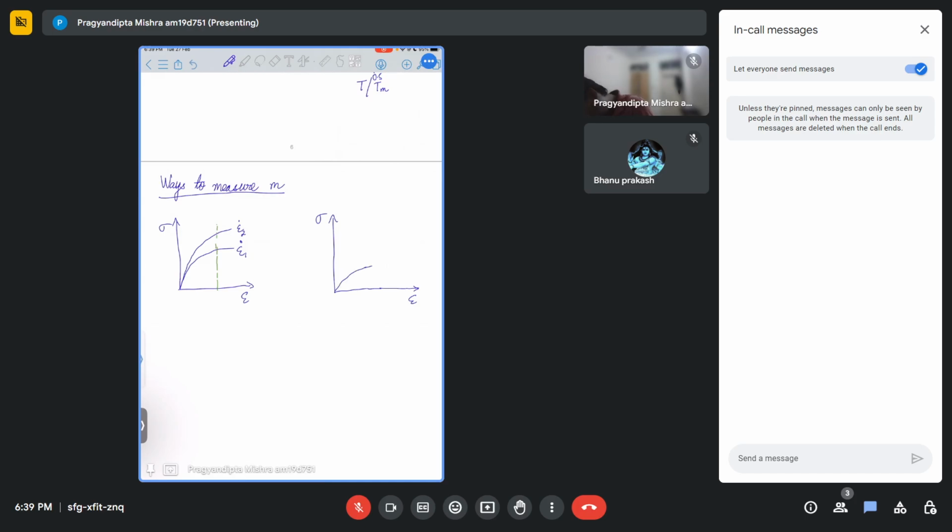Okay, and then change the strain rate. So there'll be a sudden change to a new value. Okay, so this is at epsilon 2 dot. This is at epsilon 1 dot. So I'm doing a sudden change. Now in both the cases, the way I'm finding the constant strain sensitivity parameter and C value, both of them, I can find in the same way.